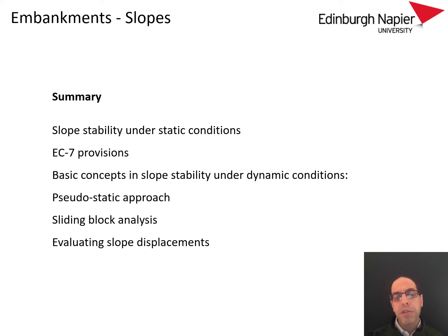And then we moved on into the pseudostatic approach following from those basic static concepts. And we finished up by showing you how sliding block analysis may be used to evaluate or estimate slope displacements during earthquakes.